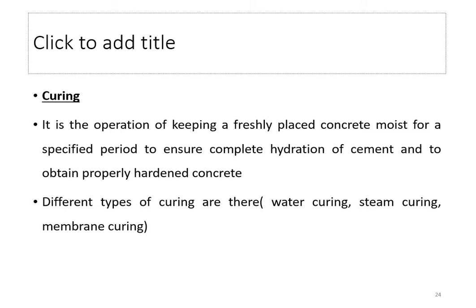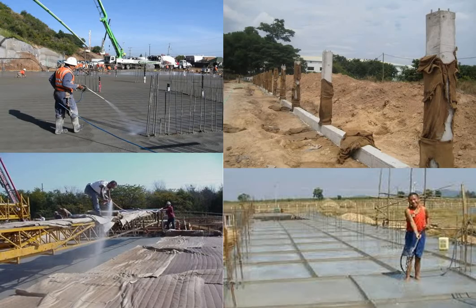It is because the water which is given for hydration may be lost due to evaporation. Once the water is lost, the cement loses its property. It needs water to complete its hydration reaction, so continuous water is needed. The initial water which was given may have evaporated, so in order to compensate for that water, you will have to continuously cure the concrete.